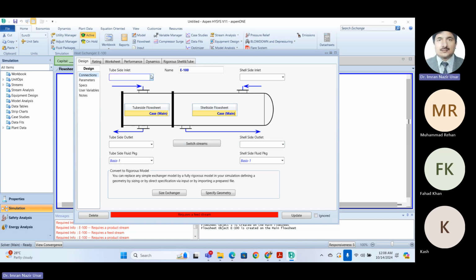Okay. So I have defined hot water as per general understanding. We have no particular rule, but it is a thumb rule or a heuristic of the process industry that we must have the hot fluid in the tube side, because hot or high temperature fluid deteriorates metal.